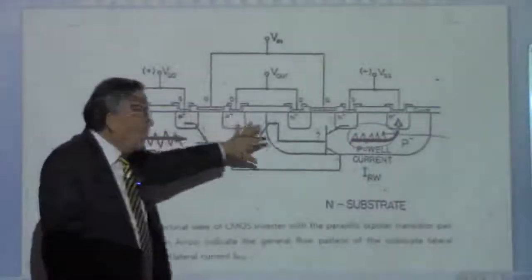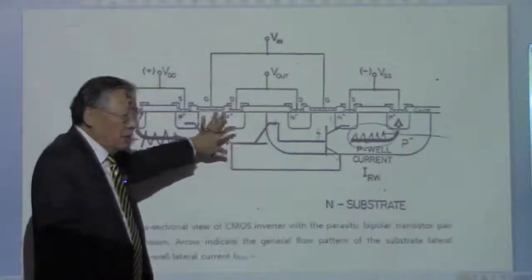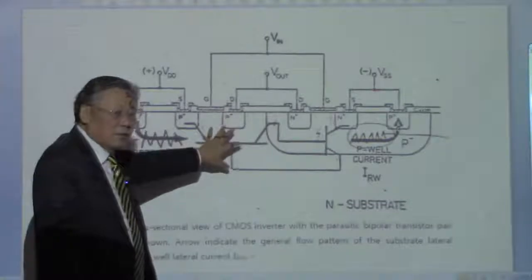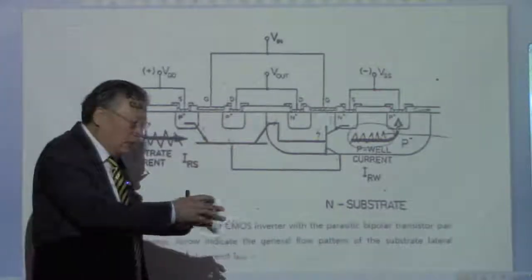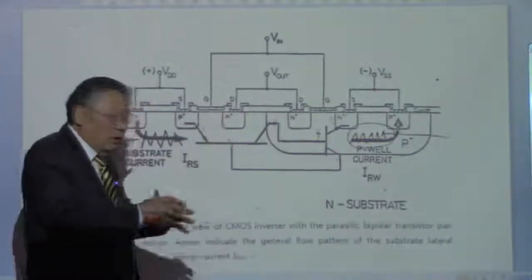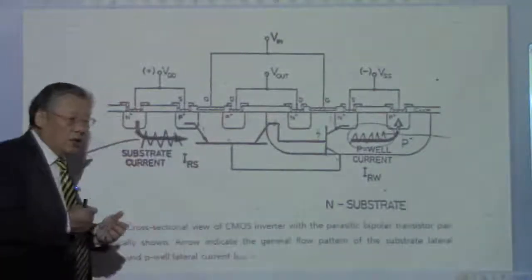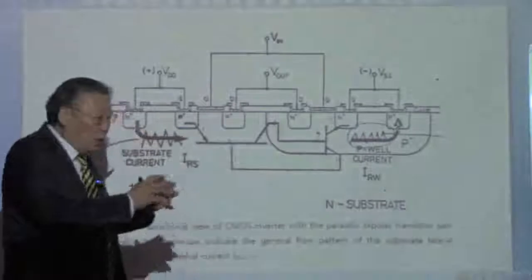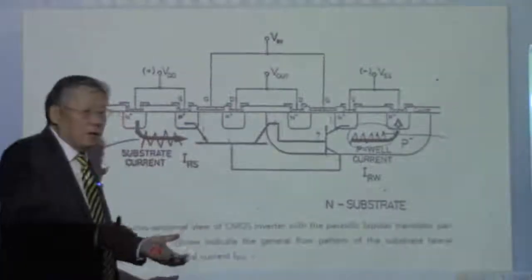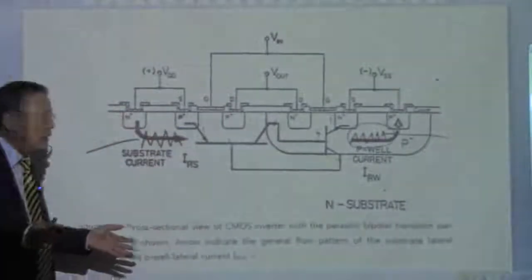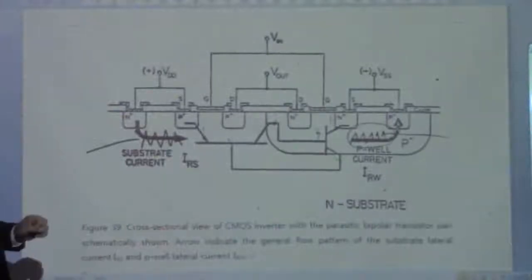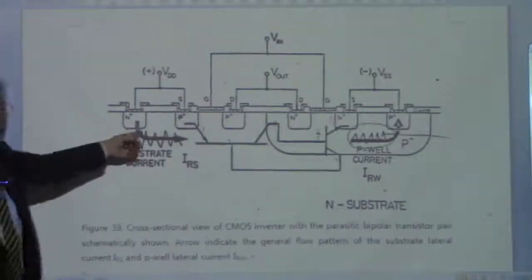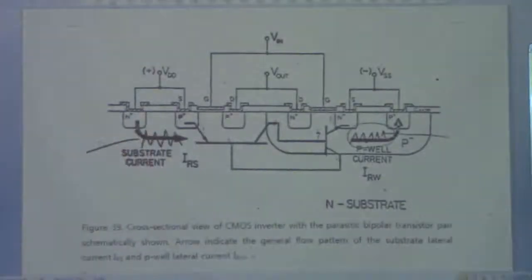You are going to have hundreds of thousands of transistors collected in a small space, and each one has Joule heating because of this high current. Then the whole thing is locally melted down, and the device is going to be destroyed. That is the problem. The current itself is not a problem at all.